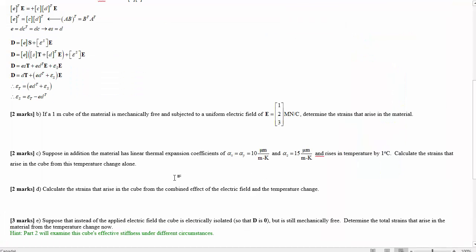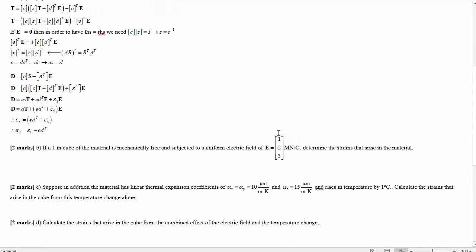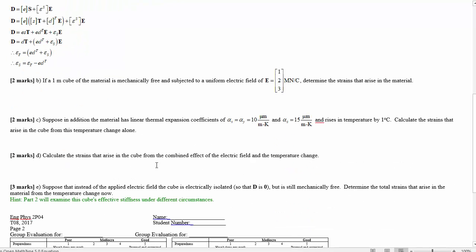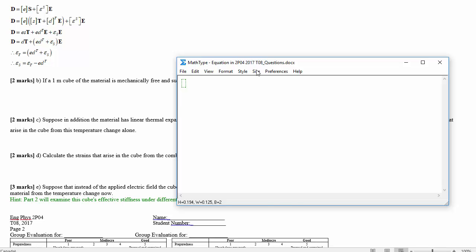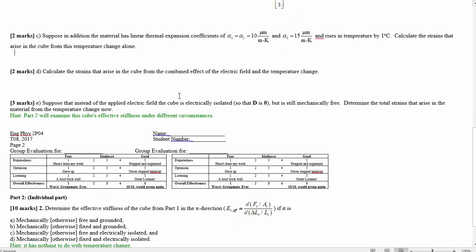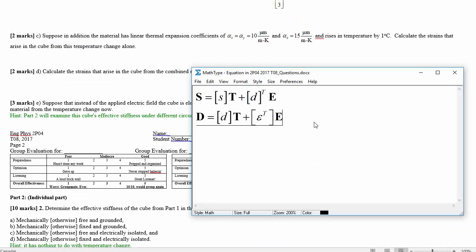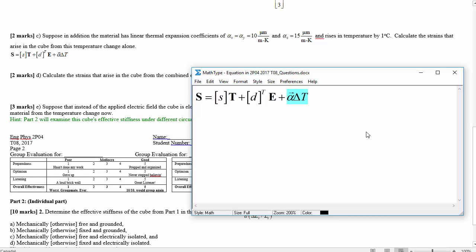Now we don't get to rest just yet, because the very next part of the question asks us to also include a thermal expansion in this setup, and that means we're going to need to go ahead and modify our piezoelectric equations. So after all of that work, we're going back and analyzing how to change these to account for thermal expansion. So we don't even get to just substitute in right away. So the first thing to do is to say, all right, well, if we have piezoelectric expansion, then what that does is it modifies the strain. So we're going to say this plus alpha with a little arrow times the change in temperature. So that just directly gives us a different strain, where alpha is a vector made up of the expansion coefficients in all the different directions. So the shear ones are just going to be 0, but then we have these things in those different directions.